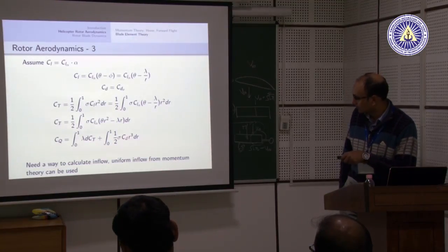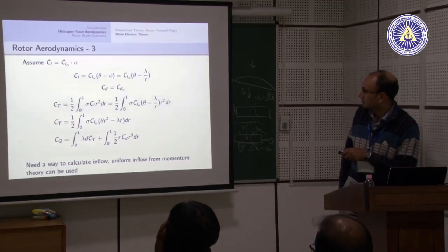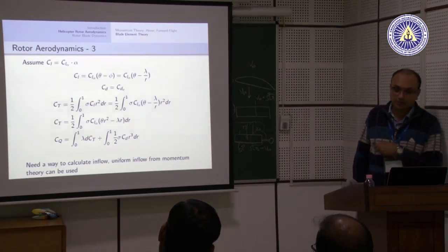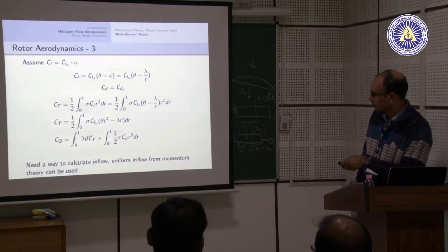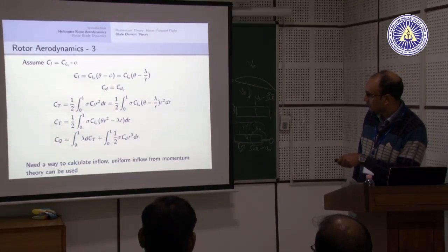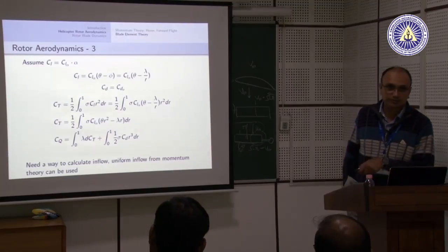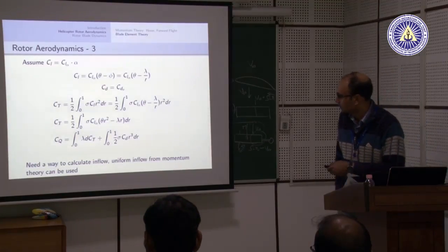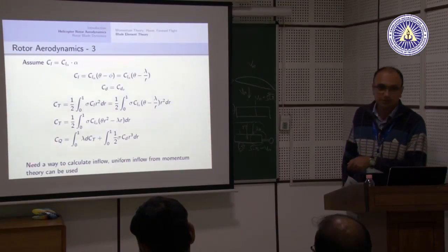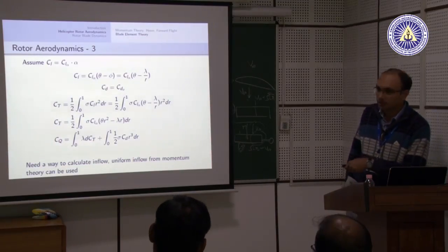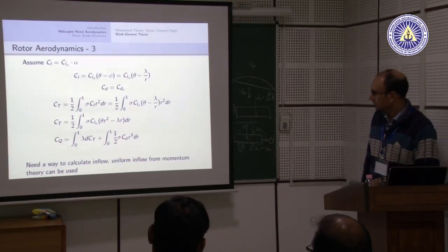It is also somewhat part of the CD sometimes, if your drag is a function of theta or angle of attack. If it is not, then this part is more or less constant, and torque is directly going to change with the way theta changes, which is part of the CT. So, the relationship for CT versus theta is going to come from here and from here, and these are two key parameters which are going to be used for control, CT and CQ.